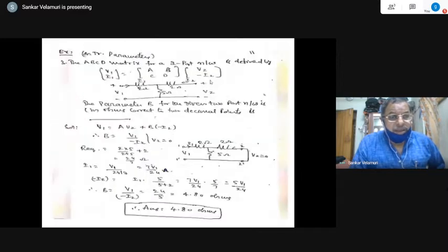Then this is also a typical problem, and finding just B is a transfer impedance. The ABCD matrix for a two-port network is defined by V1, I1, ABCD, and this two-port network matrix is generally known because these are the only equations that are given. For this network, this is given as a T network. If you convert that into a pi network, the transfer impedance can be obtained as the ohmic value of the impedance that is connected between port 1 and port 2 only.